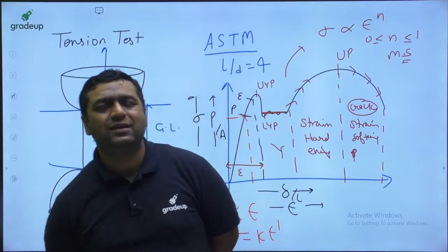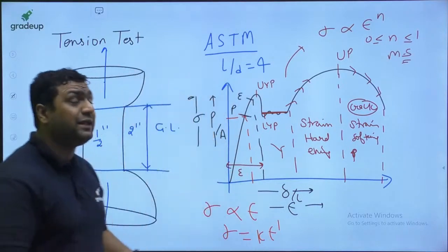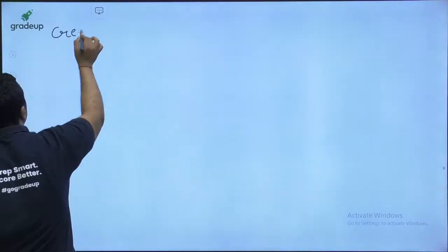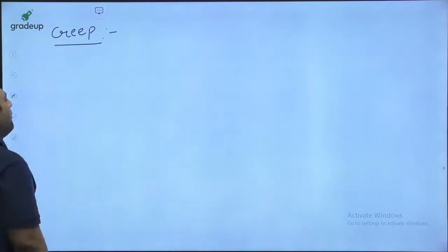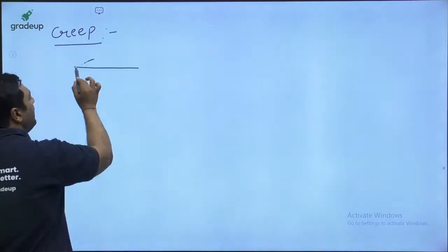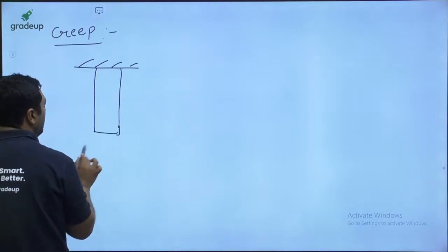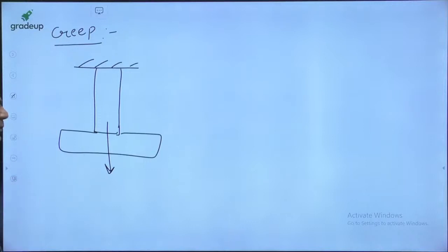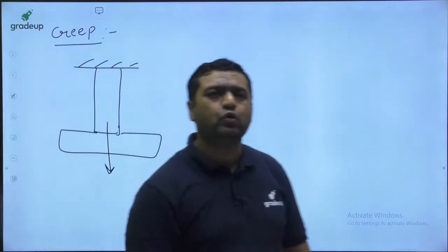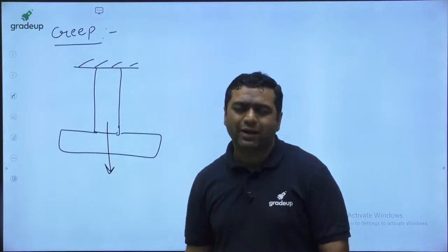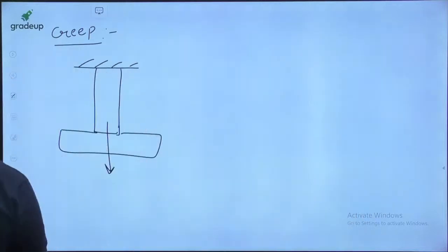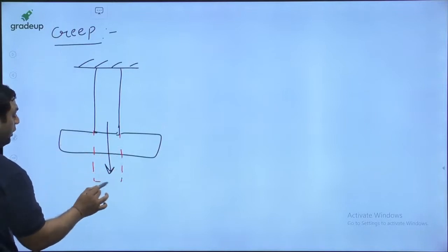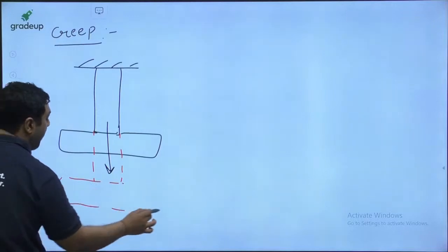So guys, today we have discussed a lot of mechanical properties. One more property is coming to my mind, that is creep. There are endless, any number of properties. My dear, let us say you have a ceiling fan hanging onto a rod. That is always applying a load onto the rod, and that load is up to the elastic limit only, because we do not allow permanent deformation. Because of this load, the body will have some elastic deformation. The meaning of elastic deformation is that when you remove the load, this deformation will be gained back by the material.